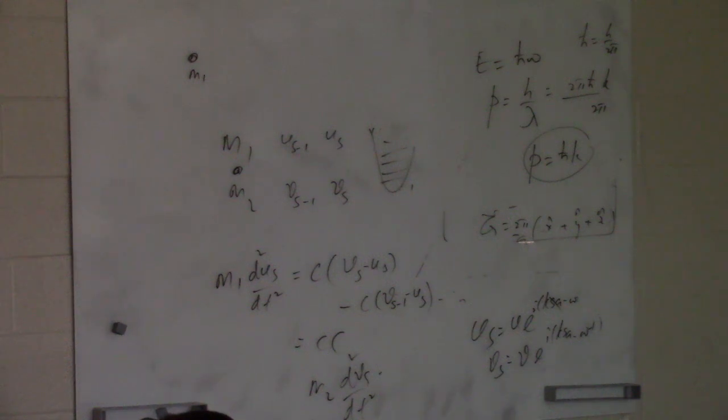So this CV is related to K by this number, 1/3 of that CV that we have here times the velocity of your phonon times what we call the mean free path. What does mean free path mean? It's phonons, right? If phonons can move without any problem, then your mean free path is infinite, right? But there are places these phonons can get scattered.